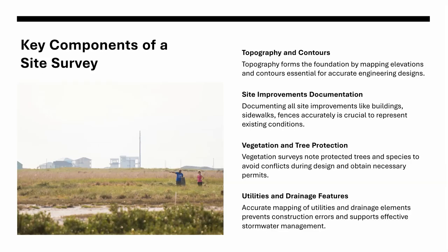Utilities are perhaps the trickiest part. A site survey must capture visible utility features. Manholes, fire hydrants, valve boxes, utility poles, pedestals, and meters. In addition to these, it must show underground utilities as marked by a locate service. This means you may be drafting based on paint marks, flags, or local reports provided by third parties. The challenge here is clarity. You must use consistent symbols and labels so that anyone reading the drawing understands what utilities are present. Confusion can cause expensive mistakes during construction.